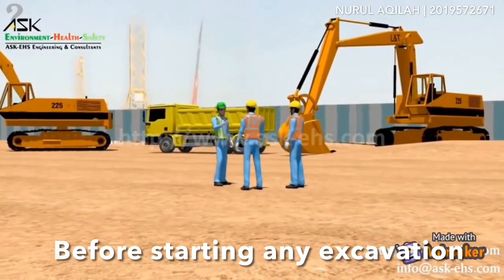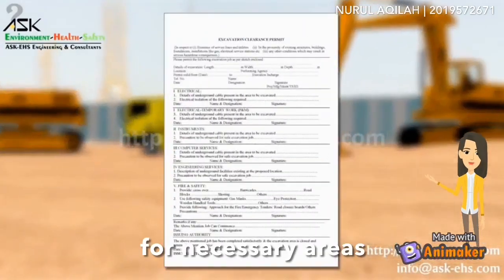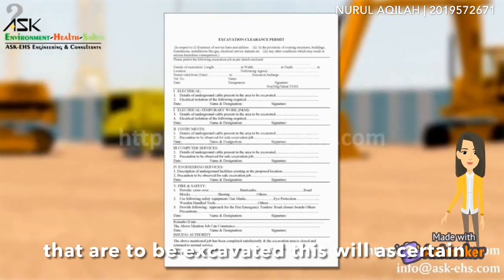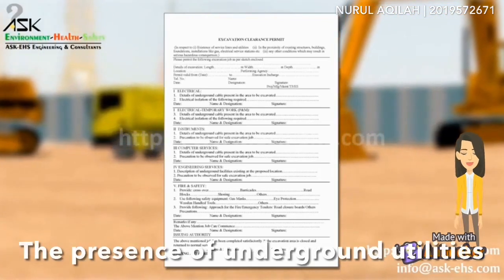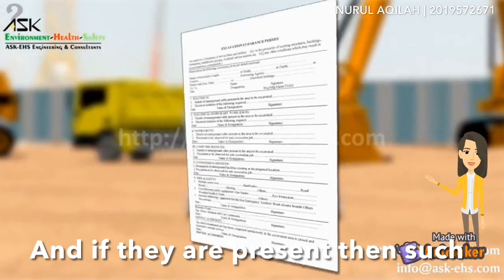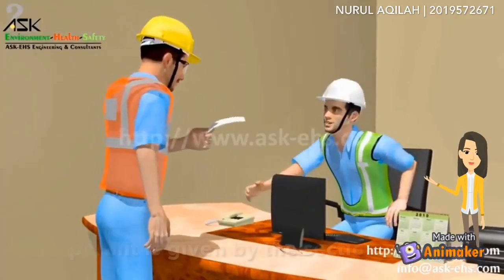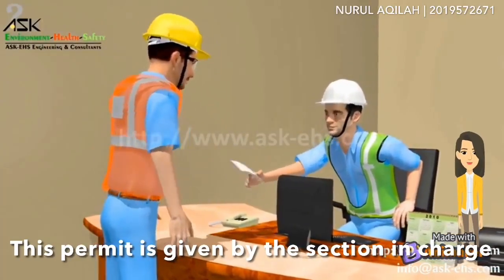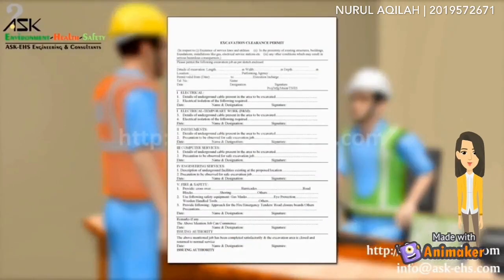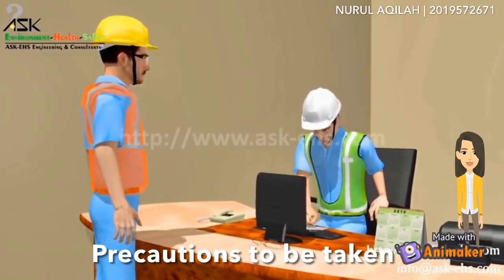Before starting any excavation, your supervisor will take a work permit for the areas that are to be excavated. This will ascertain the presence of underground utilities, and if they are present, then such utilities are properly isolated. This permit is given by the section in charge, and it is a clearance to start excavation, and states the corresponding safety precautions to be taken.